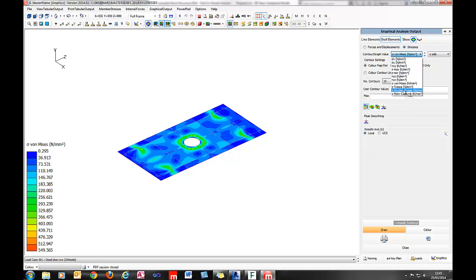And there are actually newer inputs in the material definition, so if you are wanting to get these types of stresses for the brittle type materials out, in the input of the finite element material property, you get to specify what the compression and the tension yield stresses are for your material in order for these equations and yield surfaces to produce what you want them to produce.